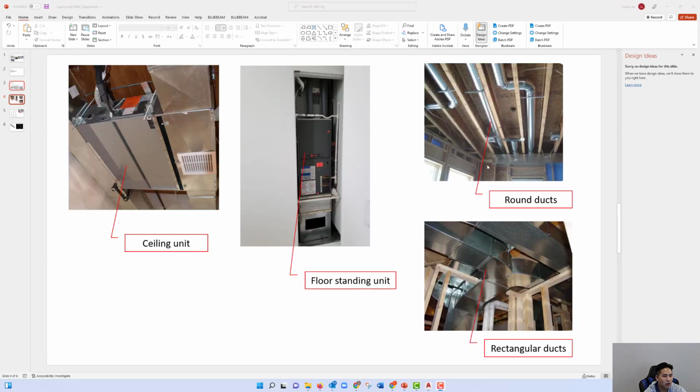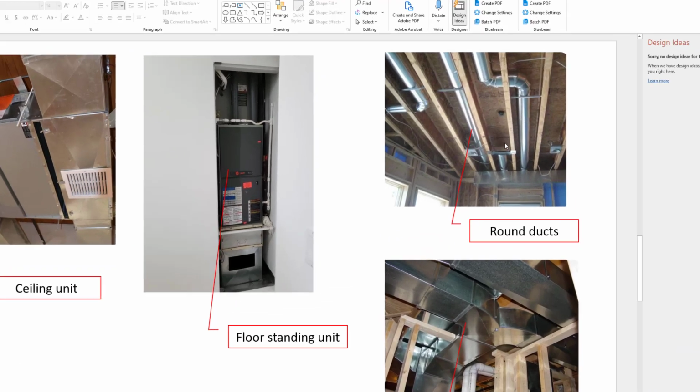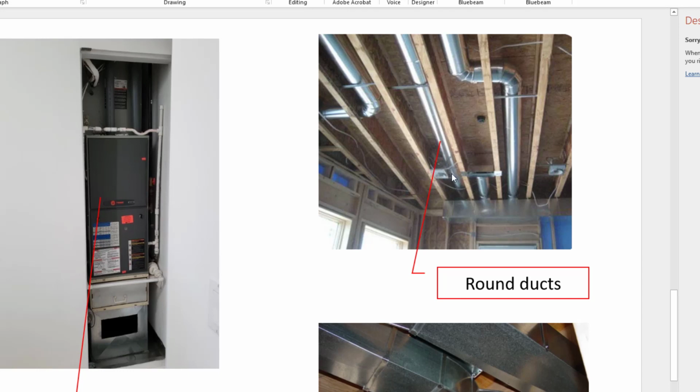And in these two pictures on the right are two examples of how ductwork is routed above a ceiling. These two pictures are shown without the ceiling attached, and if the ceiling was attached, it would actually attach to the underside of this joist, and all this ductwork would be above the ceiling that would be installed. And if you look back here, these are actually light fixtures. So sometimes when you route ductwork, you have to avoid these light fixtures because they actually go up above the ceiling by sometimes 4 to 6 inches. So you have to account for that when routing your ductwork.